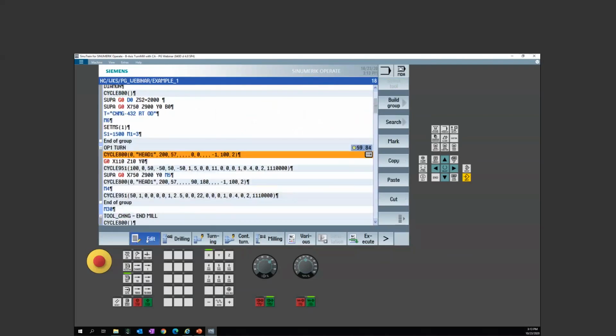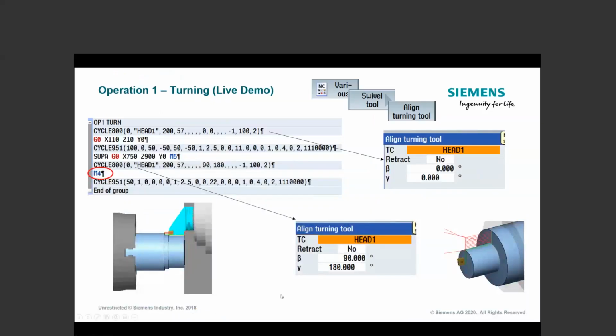And then away we go, right? Now we can start flipping that cutter. Now you do have to be careful. If you put the orientation angle in a scenario where the cycle doesn't think it's appropriate for that cutting edge direction, our cycles will still do some error checks to tell you that you have the wrong tool orientation selected. Certainly if it's straight G-code, there's no trapping at that point. It doesn't know. So it would run, and potentially it could overcut or undercut.